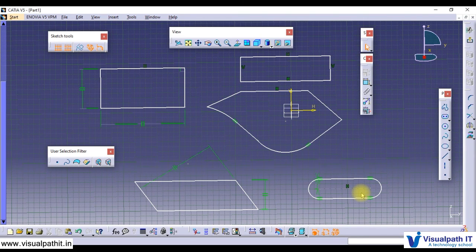Elongated holes are generally used because you want flexibility. Let's say the other end is a hole and you fixed it, and sometimes there will be a difference in the position of the other hole. That is when you use this elongated hole, so that you give the other end a small margin, so that the same part can be used in many other variants, not just one. That reduces the diversity and the number of parts.